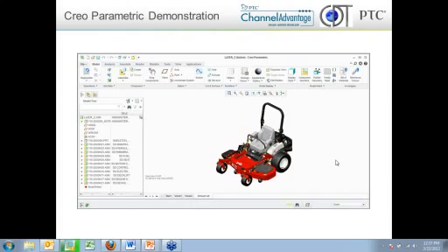But also another method of doing that within a specific assembly is I can create an envelope, which has very similar functionality. However, simplified reps are not limited to specifically just envelopes. Envelopes will take all of the components and create a new part, basically, that roughly approximates the location of all the old parts and hides the ones that you don't want to hide, and maybe facets, and then you get into shrink wrap and things like that, which can get pretty complicated pretty quick. That's why they call it the advanced assembly extension, and unfortunately it does get pretty advanced.